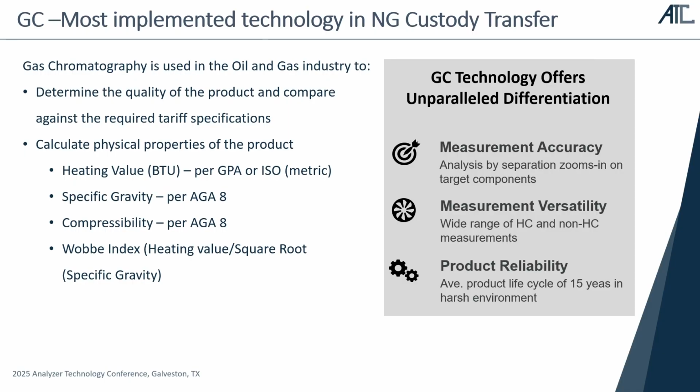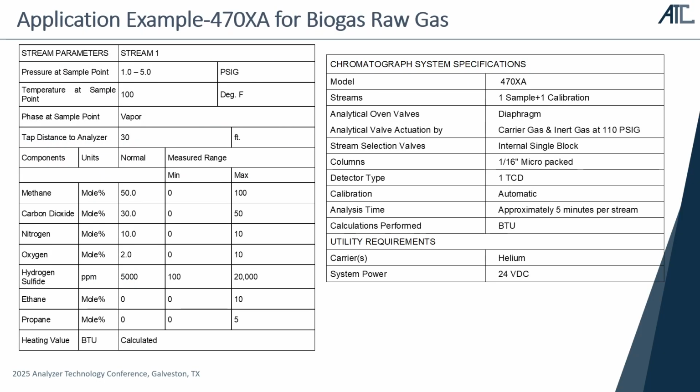And also GCs are usually designed for use in harsh environments. A lot of GCs are suitable to be installed outdoors and work for many, many years. Like 15 years is very common, right? So, due to the similarity between biogas and traditional natural gas measurement, GC technology is being widely adopted in the biogas industry. So I'm going to share 2 examples